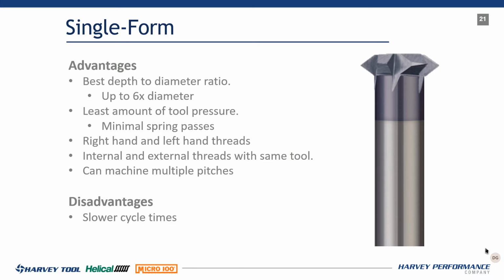That's the threads per inch. That's TPI, threads per inch. That's your pitch that you're actually running. You can run that. That's why I like a single form thread mill. Not only the fact that I can go deeper, but I can use it for multiple pitches.